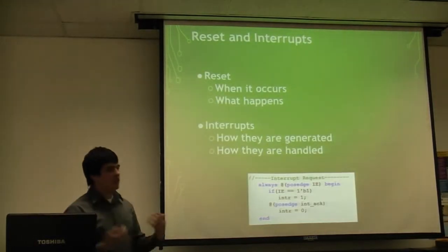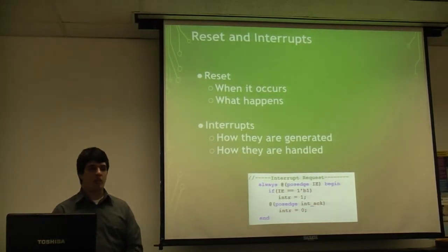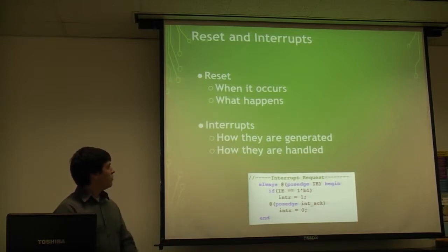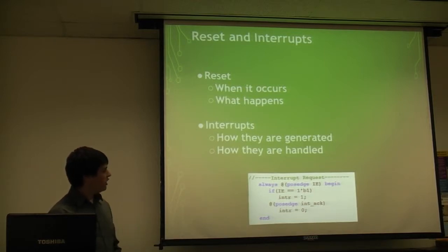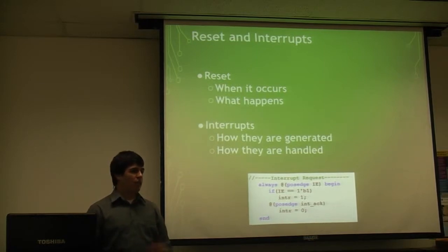So the resets and interrupts, we implemented them. We hope it's unique. Basically, the processor will not start unless a reset is implemented beforehand in the program. When the reset is implemented, it sets the IP and the stack pointer to their default values. Interrupts are generated in a peripheral I/O module just for simulation purposes. We implemented it at the interrupt enable. This part right here would normally be an interrupt request, but again, this is just for simulation purposes.